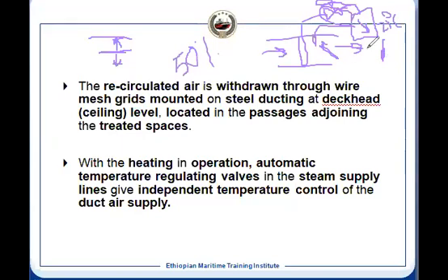Thank you. Okay. So when we are maintaining 21 degrees and the measured value is 21, the best position will be 50%. This is the 50%. This is fully closed. This is fully open. If it is fully open at that position and the measured temperature becomes 20 degrees centigrade, then what will happen? You need more mass flow of steam to the heating coil, but it is already fully open. It won't be able to adjust that. So the best position will be 50%, so that you can open this side 50%, and if the temperature is increasing, we can close it.